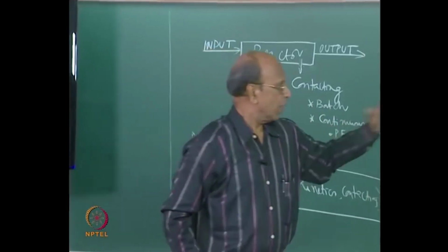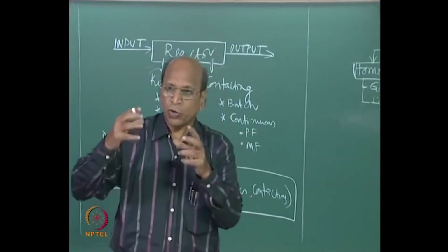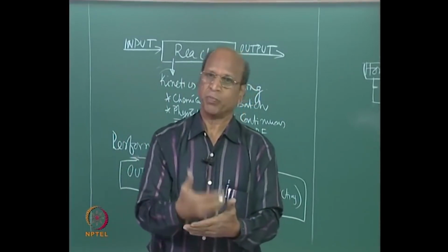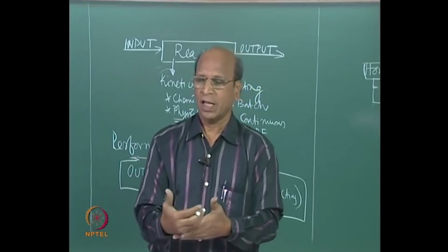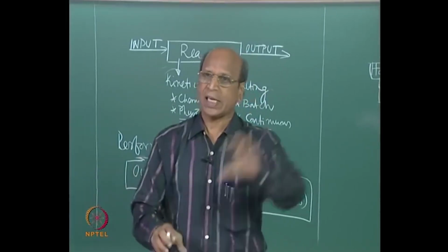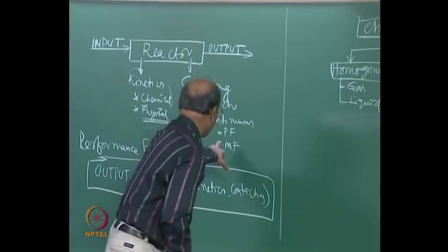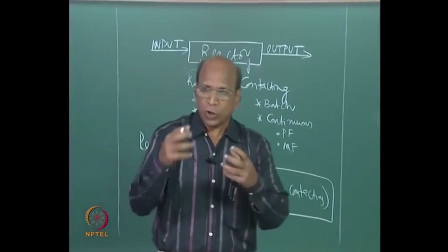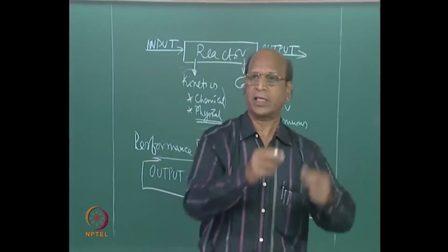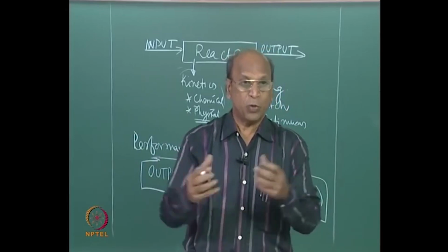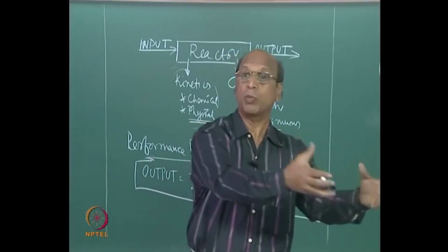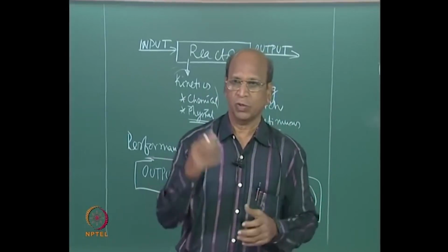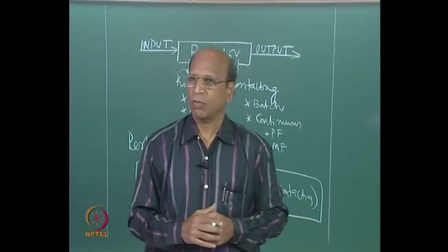That is why in reactor design, whatever you express the rate of reaction on, whether volume of reactor, weight of catalyst or surface area, you will get directly in the final result when you are going for this design equation. If I use my rate based on weight of the catalyst, I will get weight of the catalyst. If I use my rate based on volume of the catalyst, I will get volume of the catalyst. But this volume of the catalyst, again there are many misconceptions there. What volume are we talking about?